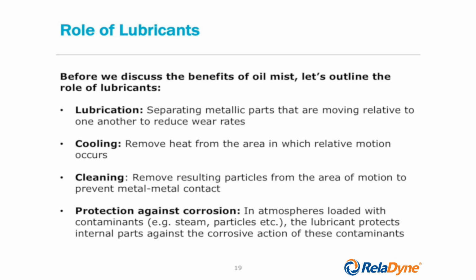A very important side benefit of proper lubrication is that we can have a cleaning effect. We can remove the particles that in some cases form in areas that move relative to each other. We can sweep them off. We can flow them off. We can eject them from metal to metal contact.